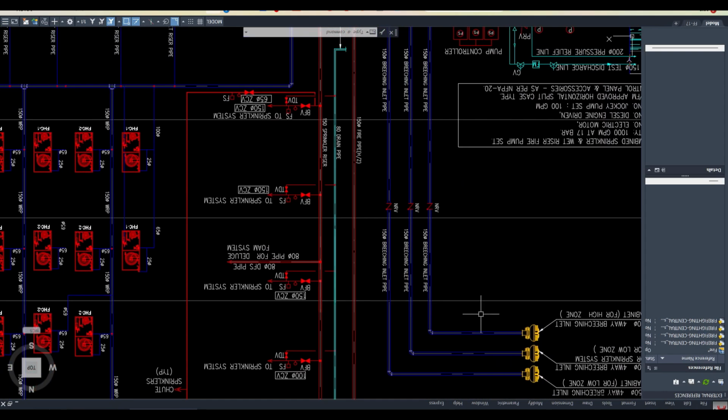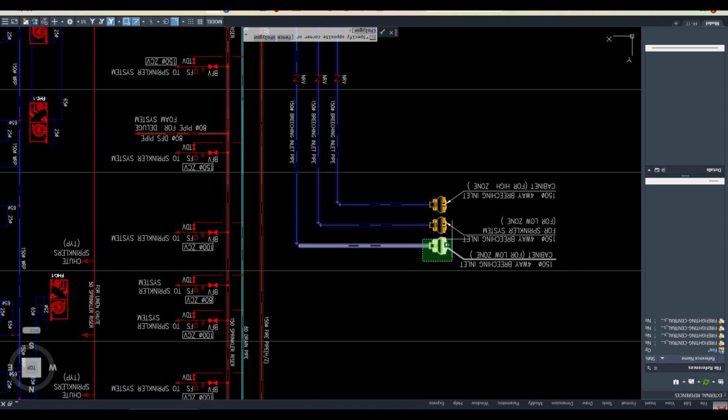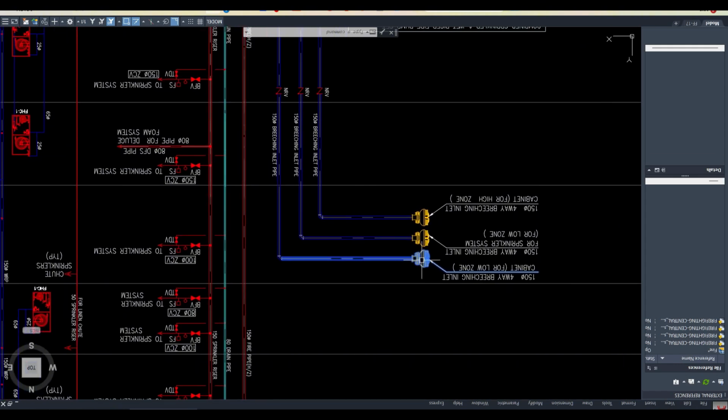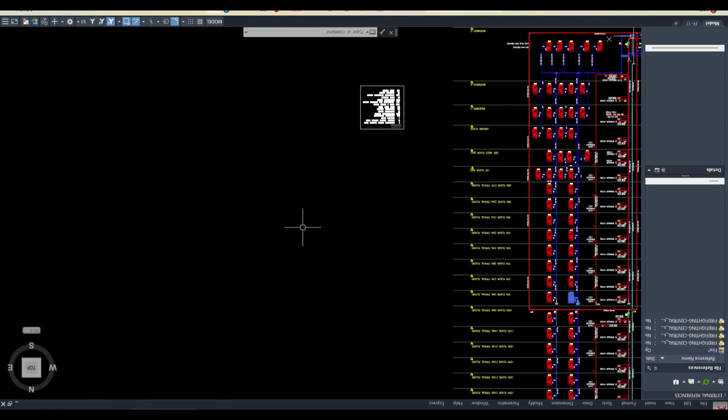Okay, now this breaching inlet should not be more than 18 meter away from the building. And it should always be in an accessible position where the truck can go and turn. Okay, so again your person is putting this, suppose your building is here.